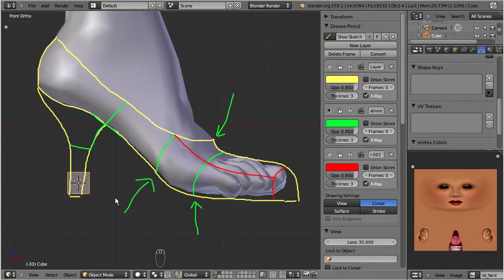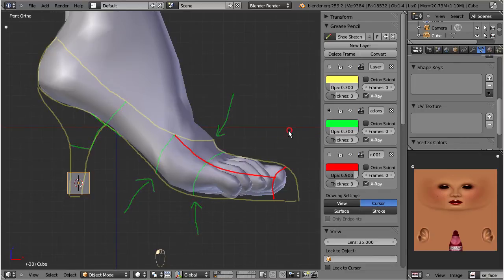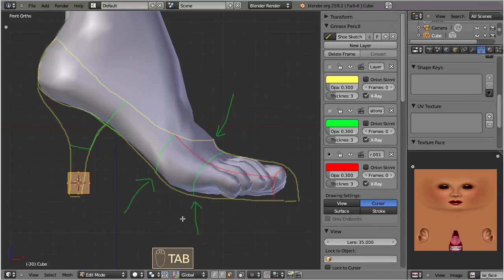And now, finally we can make the model. I reduce the opacity of the grease pencil. Then I can see better where I place my faces. I also unselect vertex clipping. Then I can better select vertices from the back side of my model.